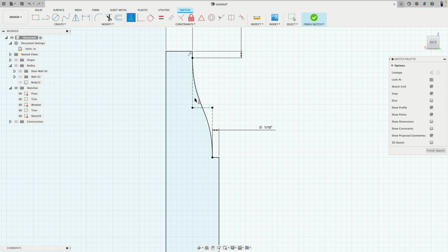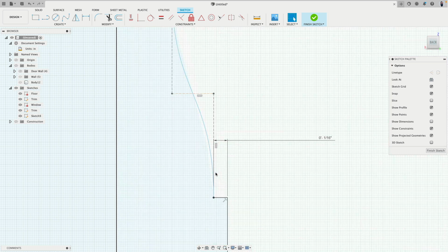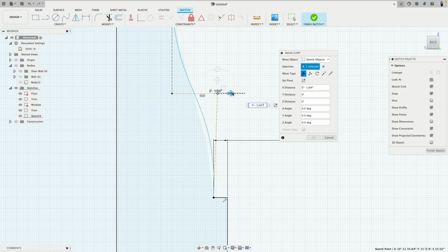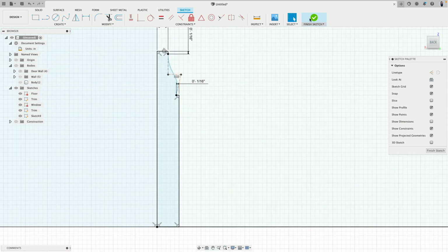Because this is horizontally and these two are equal, they're now really the same size. Very good. If I show my constraints now, you can see them now. There's this equal constraint. I can delete it. I can delete this vertical constraint. And now at this point with M, I can simply move over. So the position vertically doesn't change. It's at this midpoint. And I have a little bit more play.